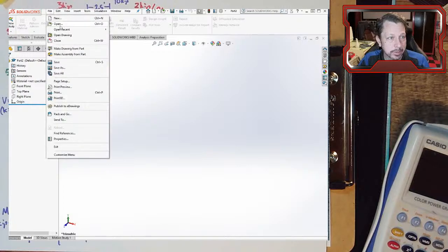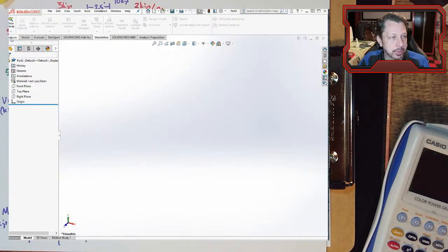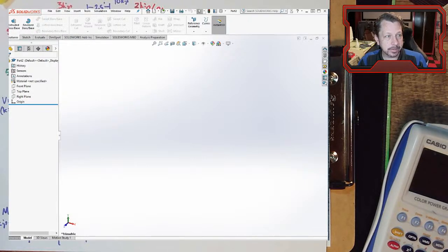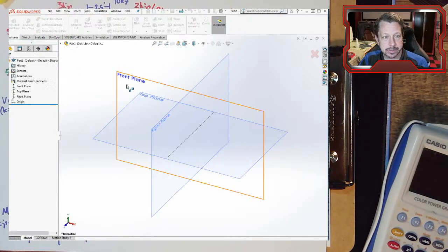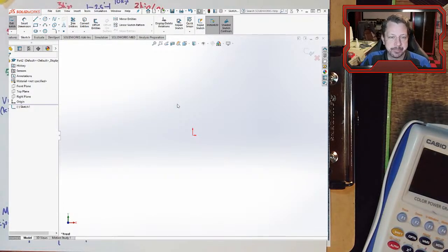So first we need to build a part though. Actually, I think I already have a new part here. We just need to build it. So these tensile test specimens, if it was a metal, like for one of the ones we just looked at in the chart, you would probably have a round tensile test specimen that would bolt into a really large machine. What we're going to do here is a flat specimen, and it's not going to be that big.